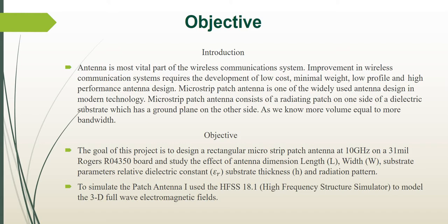The objective of this project is to design a rectangular microstrip patch antenna at 10 gigahertz on a 31 mil Rogers RO4350 board and study the effect of antenna dimensions, length, width, substrate parameters, relative dielectric constant, substrate thickness, and radiation pattern.